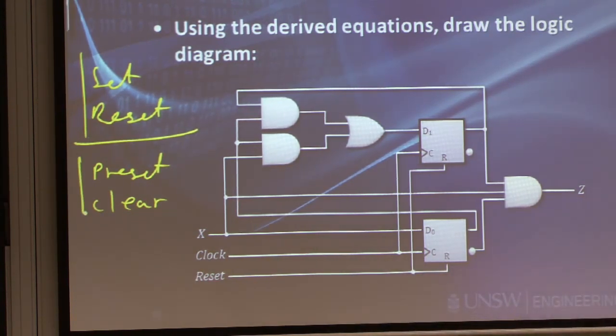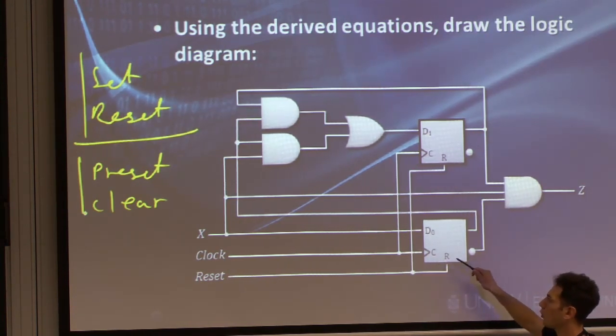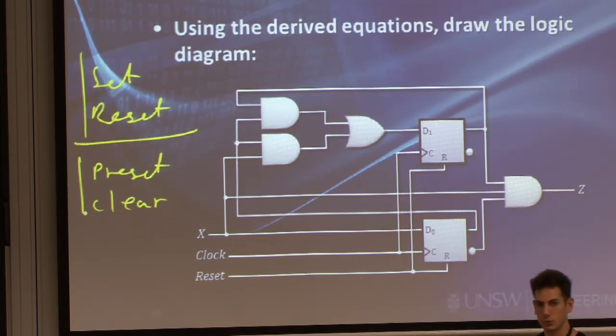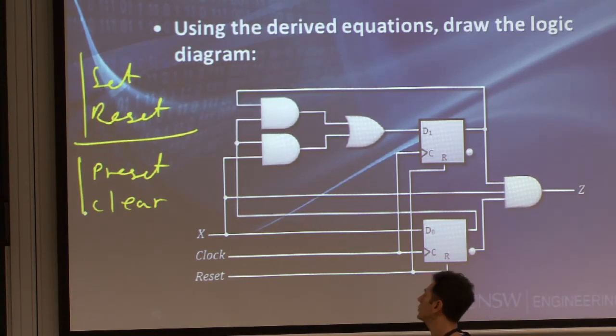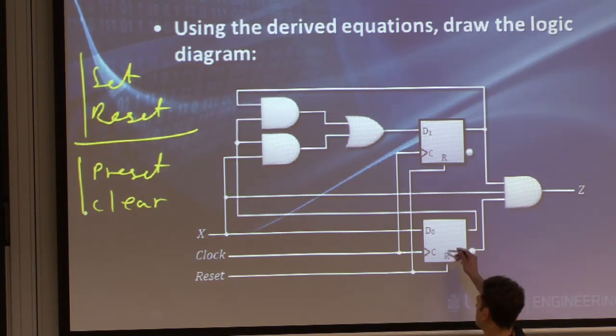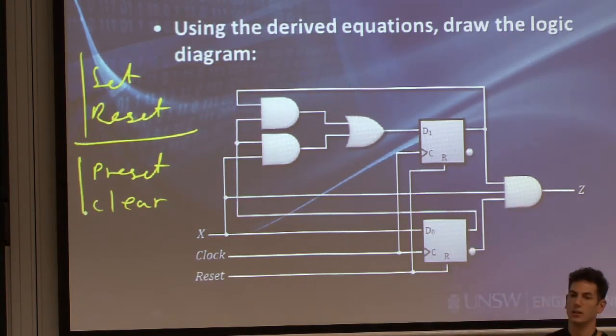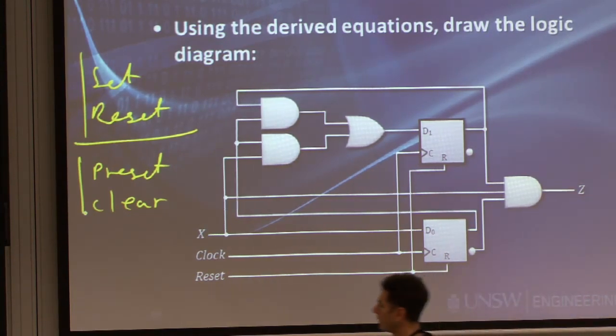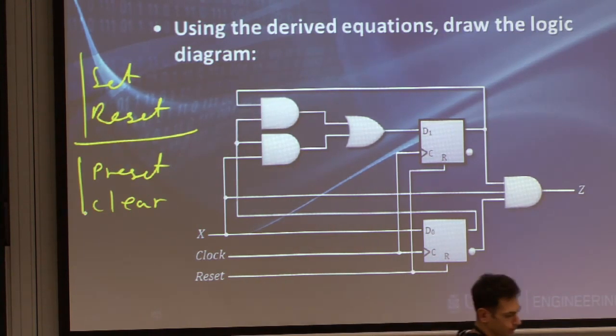What does that mean? It means that if you see set and reset signals into your flip-flops, they will not actually apply until there's a rising edge of the clock, and only then these will override whatever is in the input. So it's similar to pushing the value that you want instead of the D inputs, but it will only apply in the next rising edge of the clock.